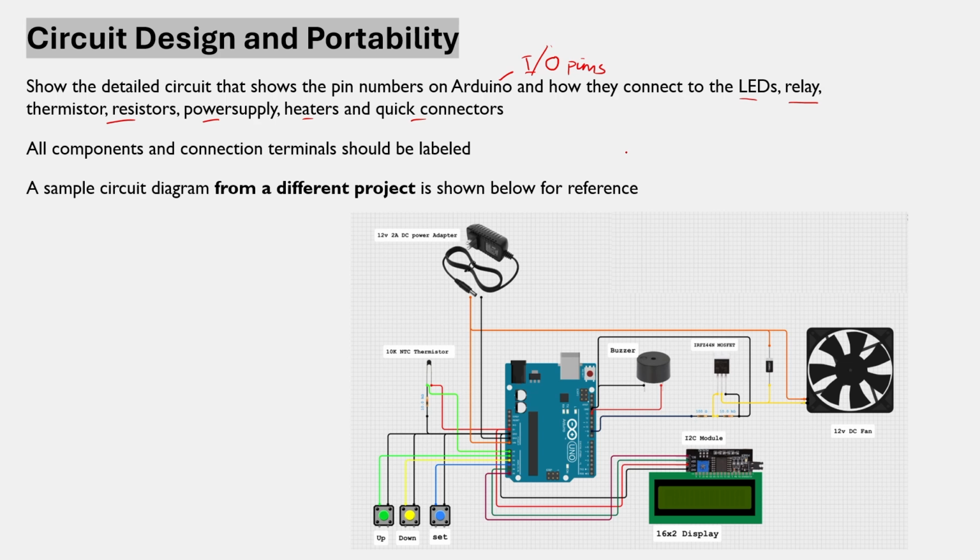So that's what a circuit diagram is. Looking at a circuit diagram, somebody should be able to copy your circuit. Okay, that is the purpose of a circuit diagram. If you give me your circuit diagram or give your friend your circuit diagram, he should be able to replicate it without further explanation. Okay, everything should be explained in the diagram, how things are connected, what is the power supply voltage, what is the value of every component. That was missing. So please include that in your final presentation and reports.